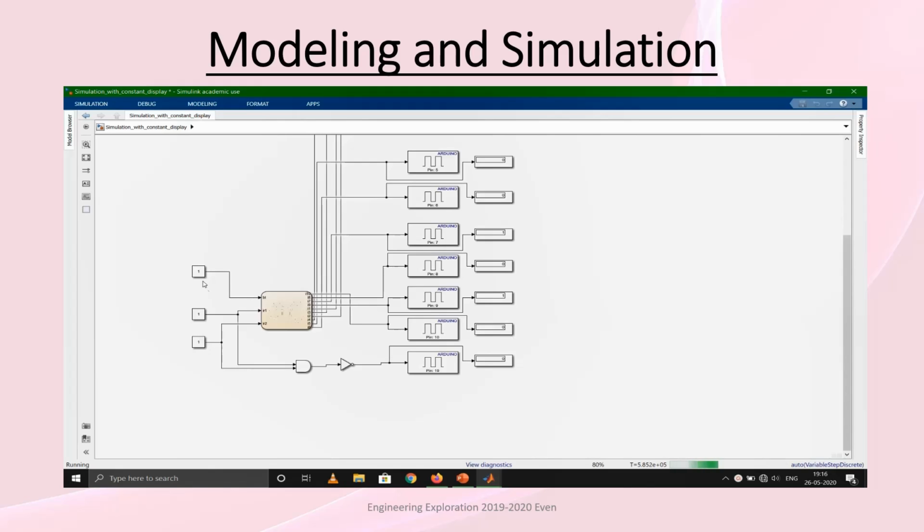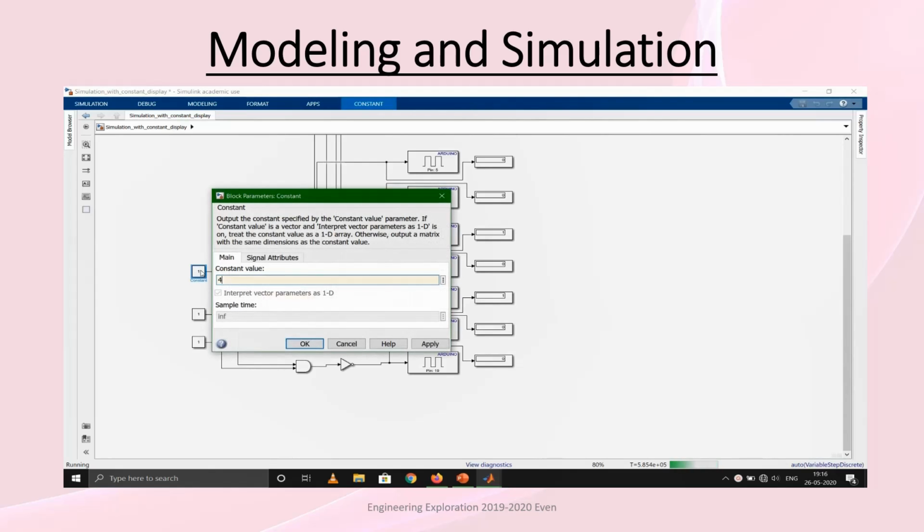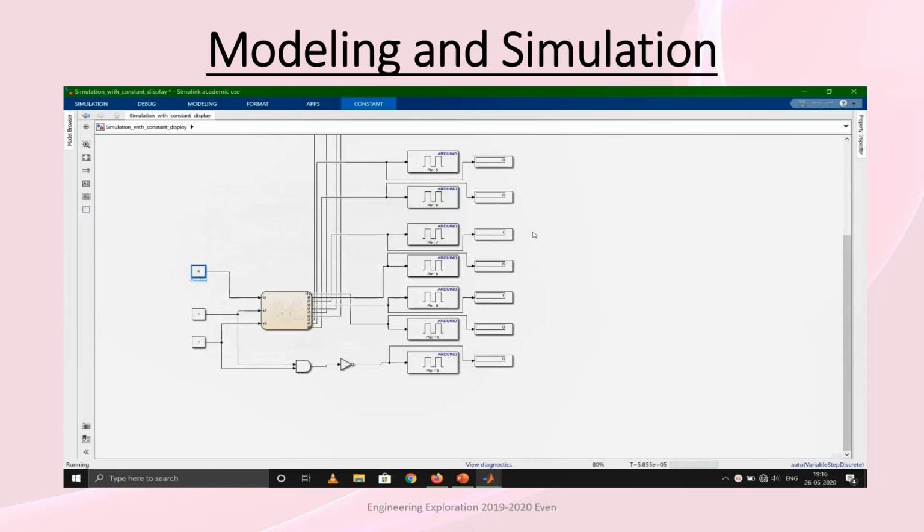Suppose we want to move the bot in backward direction. So we will give the input as 4. So giving input as 4, we can see the values change. The left front wheel now has 0, 1 and the right front wheel also has 0, 1, which indicates both the wheels are moving in the backward direction. Hence our bot will move backwards.